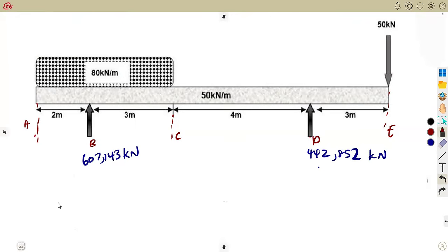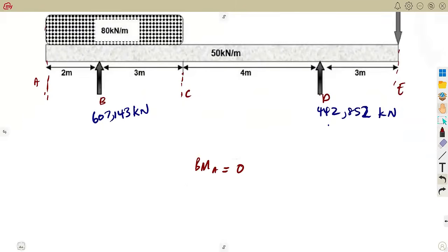We're going to consider at point A, we do not have anything on the left side of A. So meaning to say the bending moment at A is just going to be 0 there. Force times distance. We do not have any distance covered there. All right. So that is it. Remember, this is 4.12. Remember for the bending moments. Then the bending moment for B.